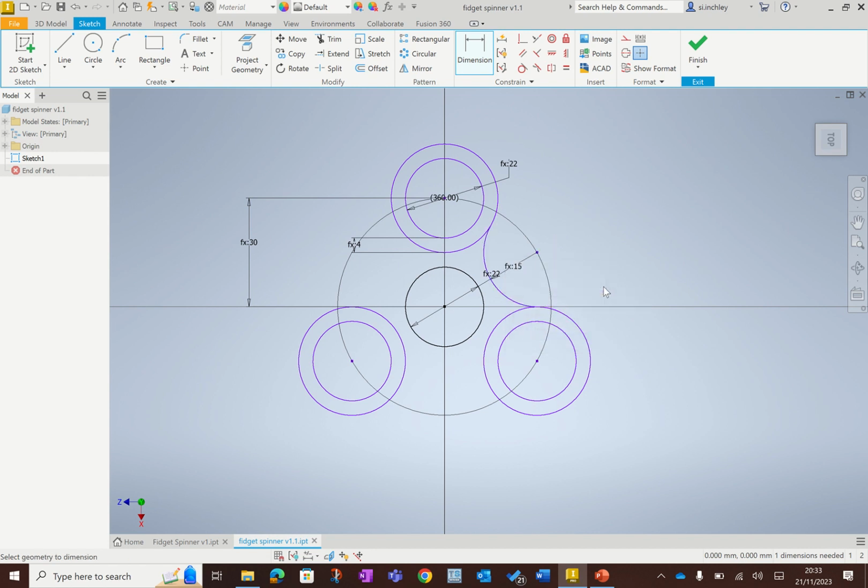I'm now going to click OK, and you can see that these points, because we selected them, we constrained them by using this tangent tool, will not move off of these circles. But now I've set the radius to 15. You can see it there. So the smaller the number, the bigger that scoop will be. And sorry, the smaller the number, the bigger it will be more scooped, and the larger the number, it will become less scooped. That's why I've called it a scoop diameter.